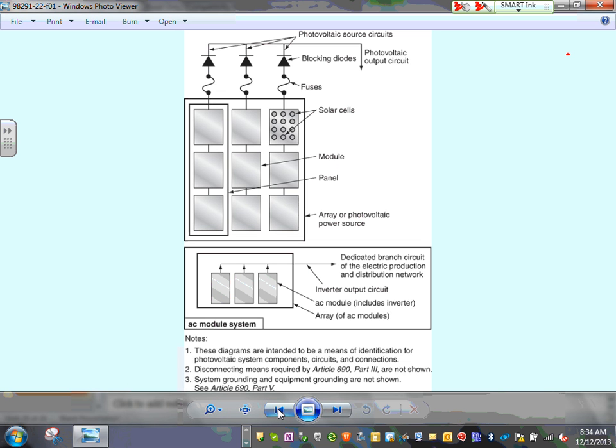A lot of disconnects. You have to learn the DC side. Derek, if you ever work with batteries and you put 2 batteries in series, 1.5 gives you 3, right? You series them, it gives you 3 volt. That's what panels are. 24 volt in series will get you 48 volt. Keep adding, like batteries. But there's a limit to how many you can add, because the voltage becomes so high the inverter can't handle it. When they reach the limit of the inverter, what are you going to do? You still need power.